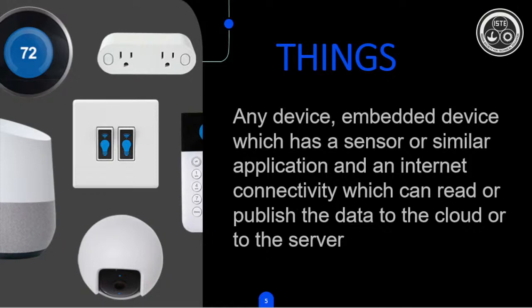It consumes around 80 milliamperes of current. So if we do some math, power is equal to voltage times current, it will consume around 0.3 watts. The embedded device is consuming 0.3 watts, and the desktop, a general purpose machine, is consuming around 500 watts. So this is why we are moving to embedded devices, and we are not using general purpose machines in IoT applications, in the things.